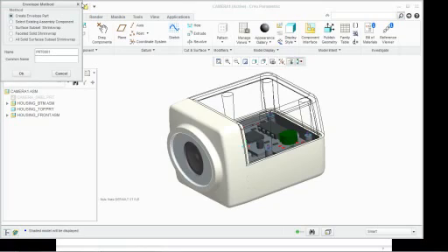You want to make sure you select all of the components in an assembly because then the envelope that I'm creating will allow me to substitute for the entire assembly. If I don't select all those, it won't allow me to substitute it for the entire assembly. So now that I've done that, I want to click All Solid Surfaces, subset Shrinkwrap, and I want to assign it a name, Solid Cam ENV for envelope.